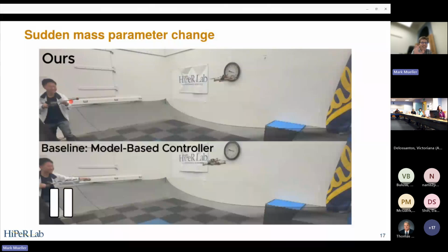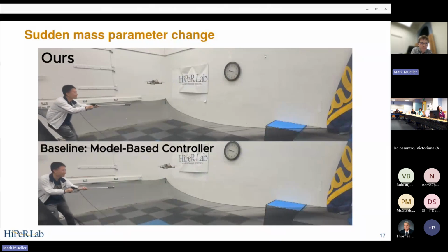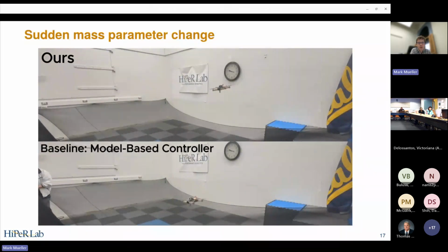Jerry will be adding a mass to a magnet on one of the vehicle's arms, and this mass effectively moves the center of mass. So it looks like a moment roughly to the vehicle. So there'll be this persistent moment imbalance on the vehicle. So we see here, if you attach this, of course, the mass changes, but there's also this moment offset.